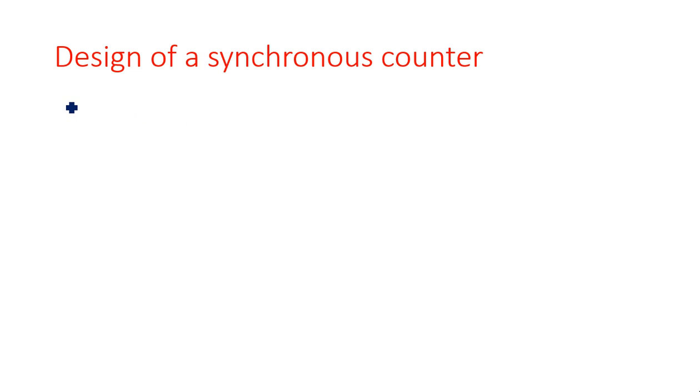Now let us design a 3-bit up-down counter using JK flip-flops with reset and clear pins. An up-down counter means a single counter has to perform both operations, up count operation as well as down count operation.